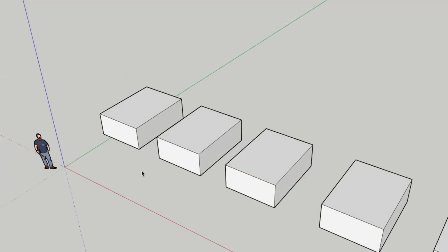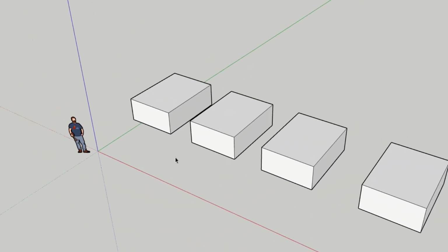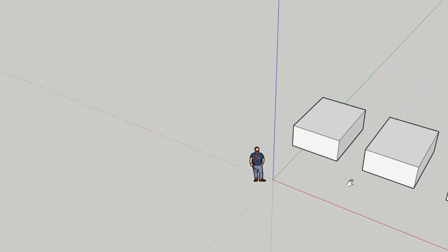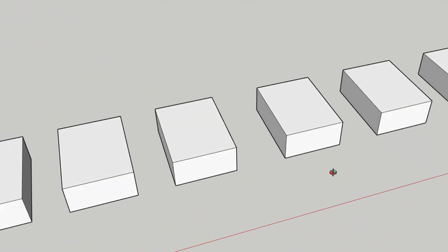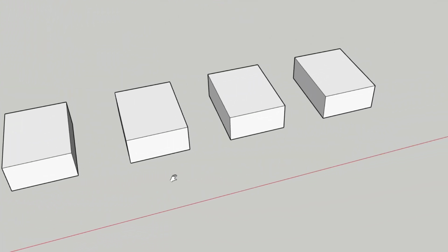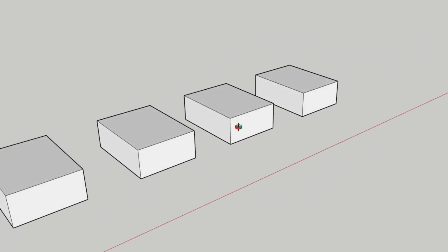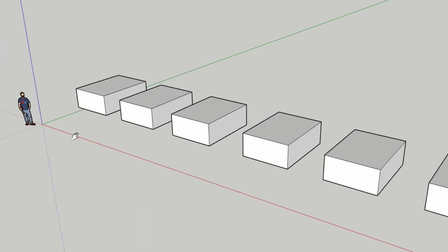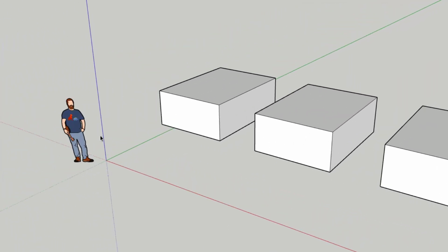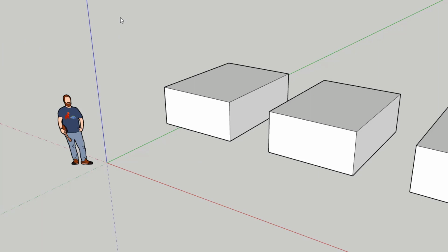To activate the pan tool, while clicking and holding the wheel, I press the Shift button and the pointer switches to this symbol of a hand. And with that, I can easily move to the sides. Basically, zoom, orbit and pan are interconnected. And to be fluent moving around our project, it's not as easy as it may look at first. Sometimes in bigger projects, going exactly to the place where we want takes some time, and I recommend starting by doing this with slow movements.